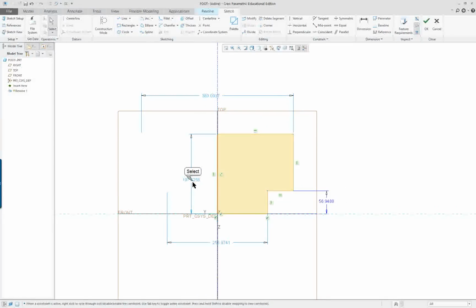No, I shouldn't say that. Here is Modify, Replace, and here is Strong. So if I make a strong dimension, then that dimension won't disappear if I add another dimension someplace else. So for instance, if I click on this and I want to turn this one into, oh, for some reason this one doesn't, oh, because I added this dimension. So this is already a strong dimension. So it's going to go there without needing to be selected and given another status.